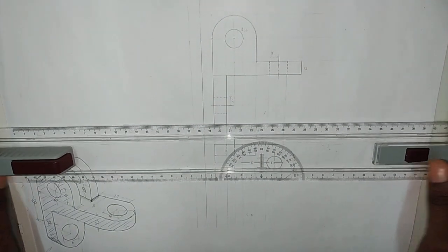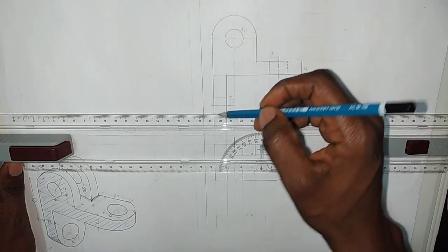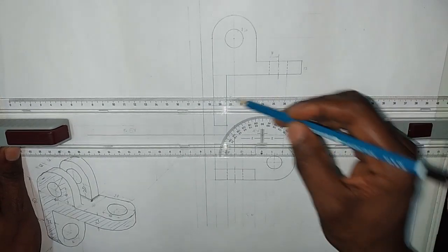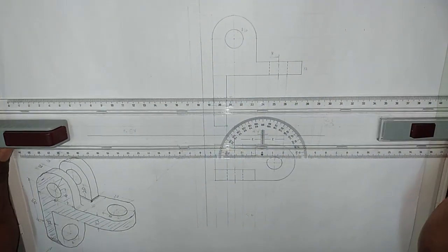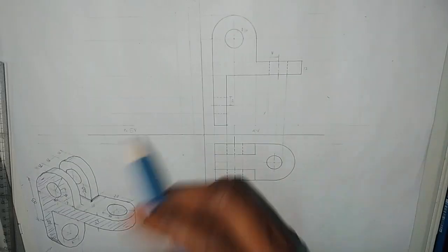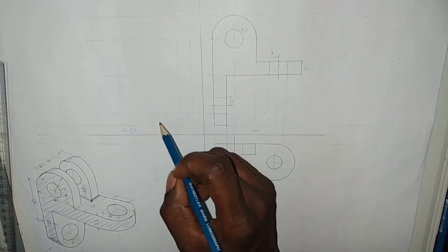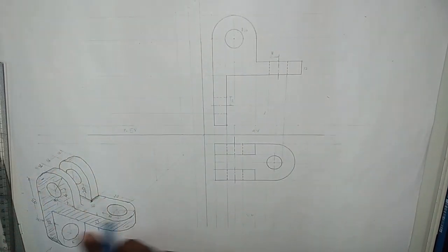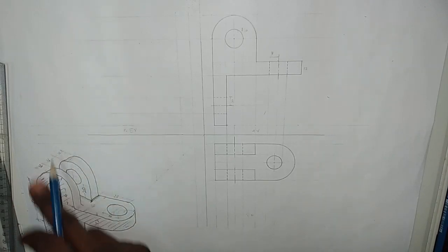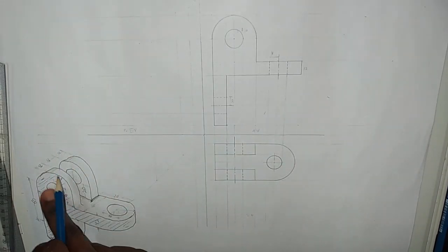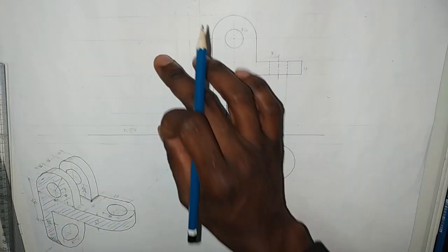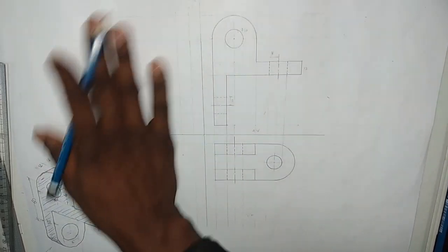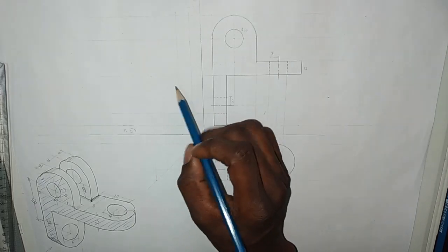We also take projection lines from over here, from the front view. So we have that, we have this. So you are producing a right end view over here, just using where the projection lines meet, and also carefully study the isometric drawing. Then use all the features and place them at their appropriate places in this view where the projection lines meet. So we are going to do that.